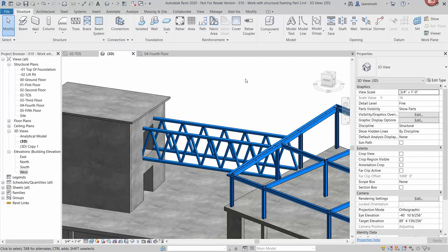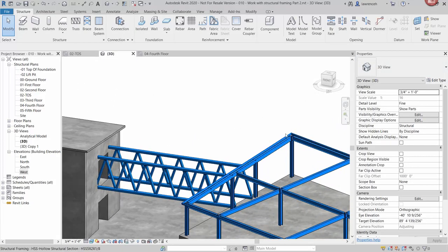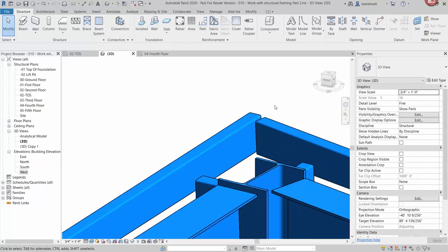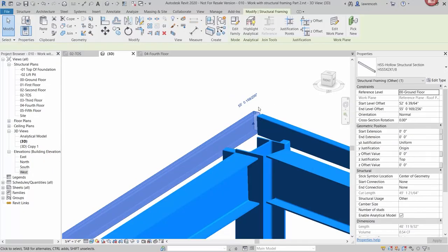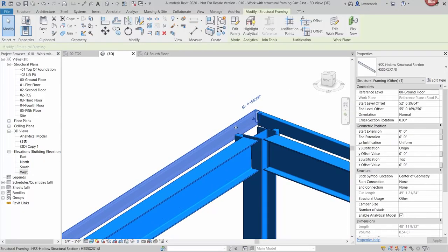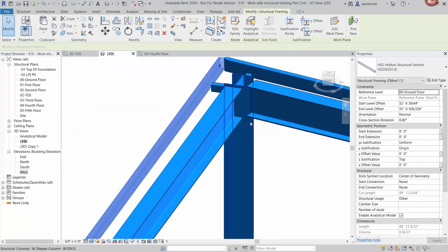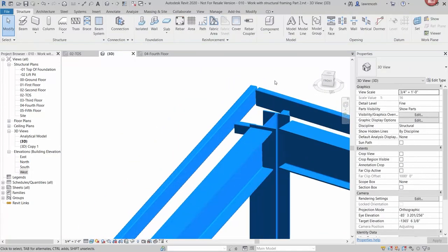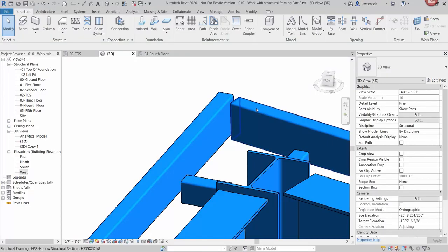Next, we look at beam column joins and coping. Let's start with beam column joins. So on the roof section here, you can see that we have stub beams over here carrying these rectangular hollow sections. And you can see if we look at the condition at the end of these RHS sections, we really need to tidy those sections up a little bit.